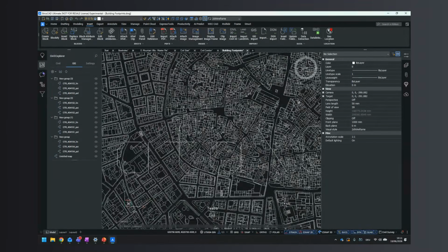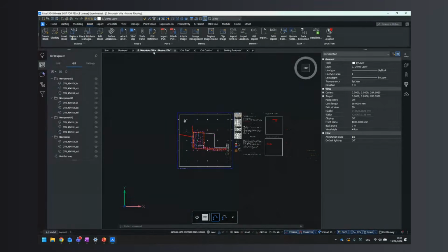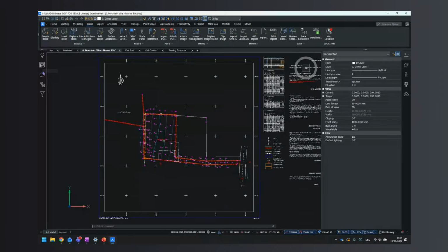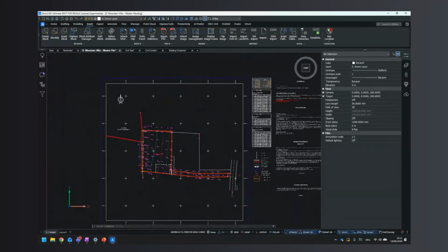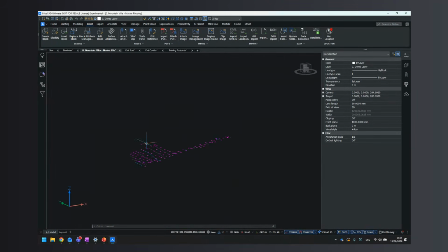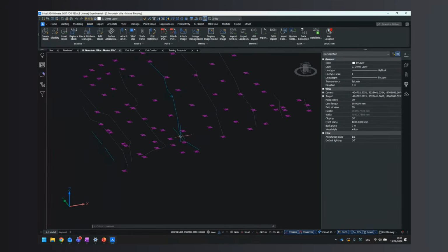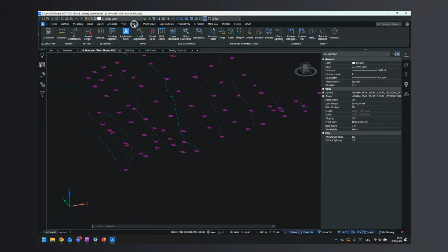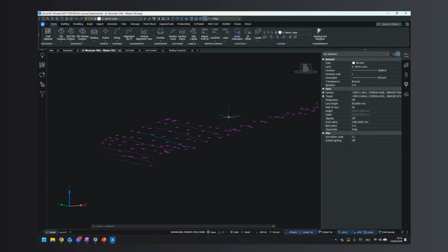So this concludes the GIS side of today's presentation, and then let's take a look at a more realistic example, shall we? So this is a surveying plan, right? We have our topography lines, we have our civil points, and if I start rotating this, you already see that the lines and points are already in the correct elevation. I used a Lisp routine for that, which can be inserted under the Manage tab, Load Applications. So Lisp is available in BricsCAD.